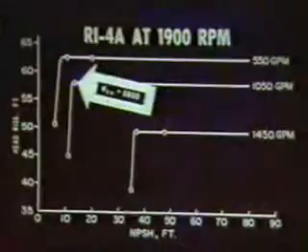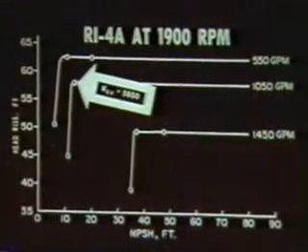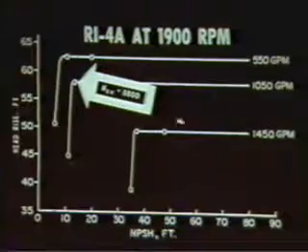The small cavitation formations are indicated by arrows. Localized cavitation exists on both surfaces of the vane leading edges, and also on the suction surface of the splitter vanes.